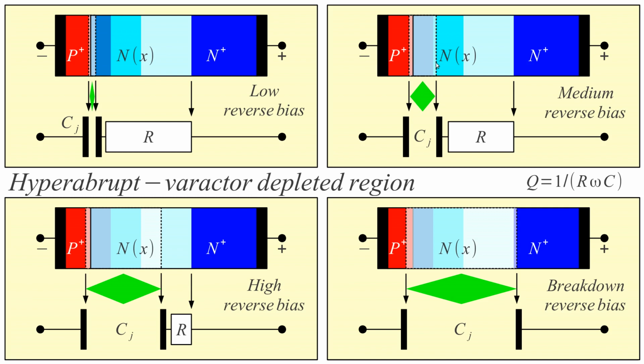But now, as we get into the lighter doped N region, so this is heavily doped, medium doped, very lightly doped, here we have very little charge. So for a slightly larger bias voltage, this edge was moving slowly because of the high amount of charge in this region, but here it is moving very quickly because of the low amount of charge we have in this region of the doping.